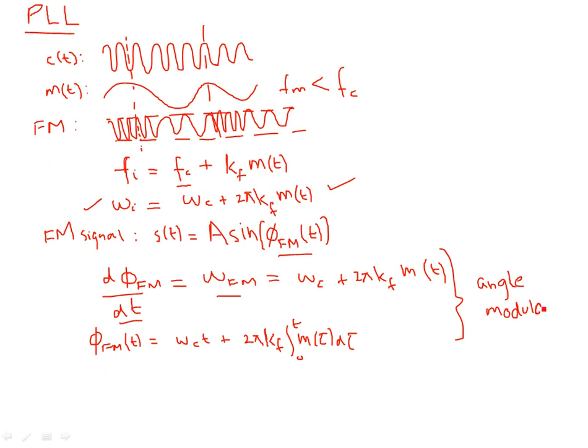So, well, returning back to the topic, how a PLL can be used to demodulate such a signal. The job is to somehow try and extract from an incoming FM signal back the message signal m of t. Well, you need to have a circuit that can track the frequency variations with respect to the message signal and can produce an output that is going to replicate the frequency of the message signal. Okay, so that will be the demodulator. Now, let's start with the basic PLL diagram.